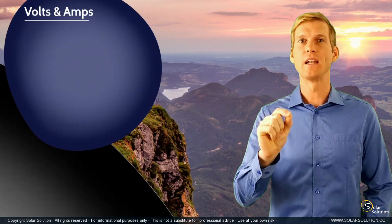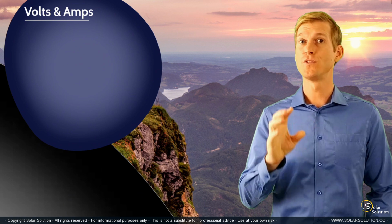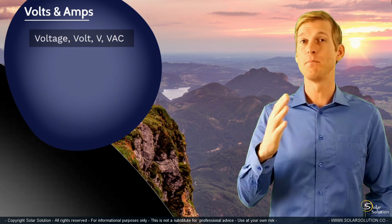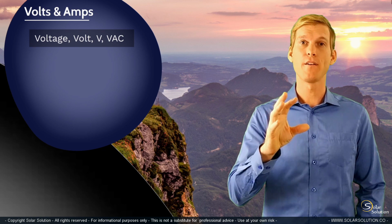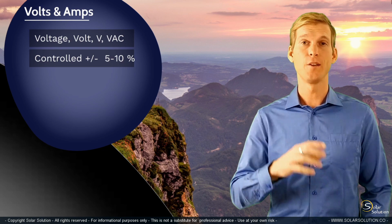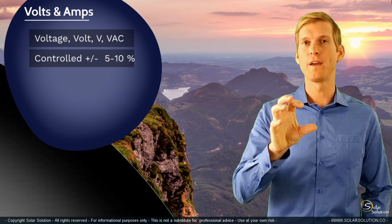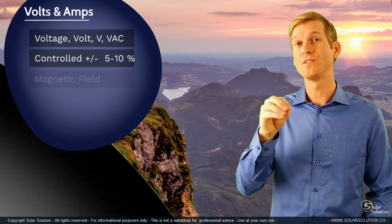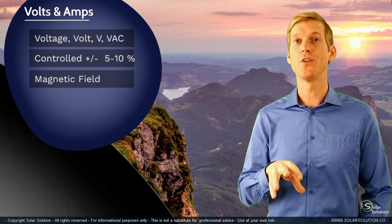So the first thing to realize is that the output voltage of your generator fluctuates over time. It depends which kind of type, model, and quality of generator you have, but it can fluctuate as much as 5 to 10% up or down. Now, your generator is able to modify the output voltage, and it does this by controlling the internal magnetic field inside of the generator, so inside of the alternator.